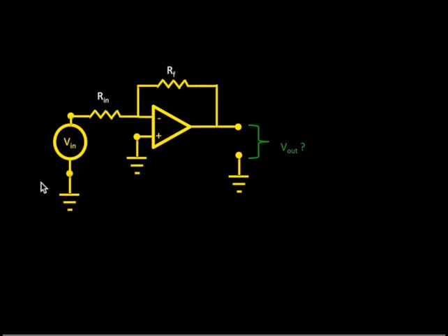Let's analyze this circuit. Let's start by making some simple observations of current and voltage wherever we can. Now, the most obvious thing to do is to see this ground and say, oh, okay, the voltage at that point has to be 0 volts. Well, that's equal to the voltage at the non-inverting input, so V plus is 0. Now, we see that there's a feedback loop, so the op-amp is going to try to drive the inputs to match in voltage. So this one has to match this one, so the non-inverting input's already set, so this voltage has to be 0 as well.